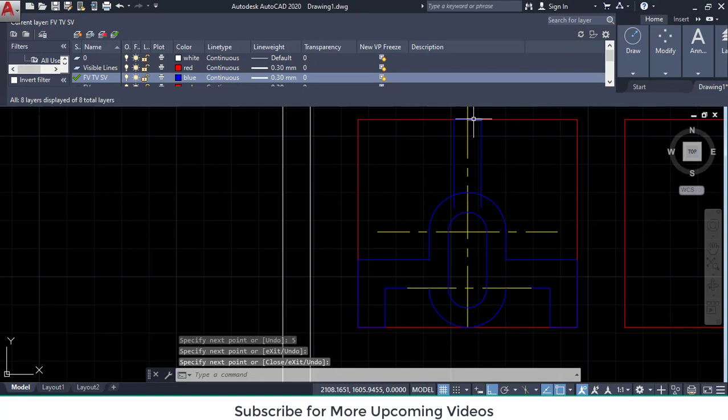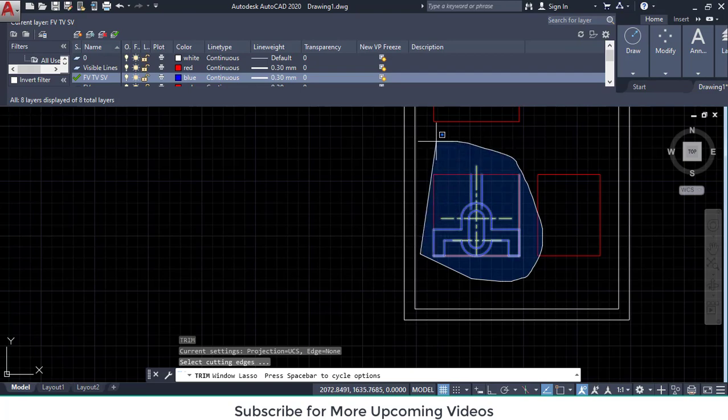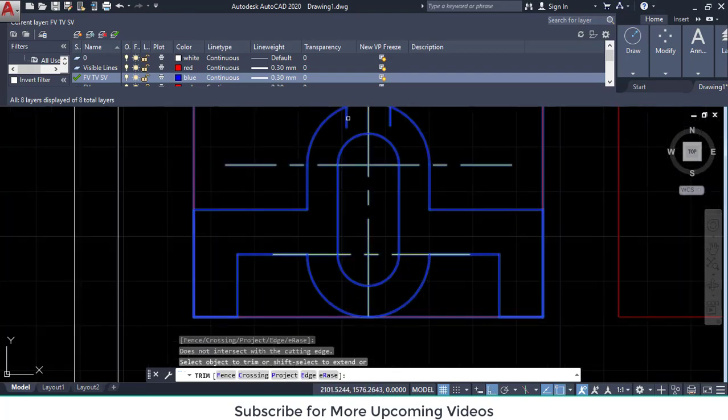Now delete these extra portions and trim these extra edges. So we can use trim command, enter, and trim this extra portion and this extra portion.